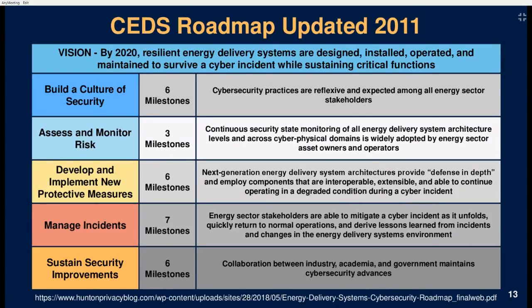I arrived at the OT community only 5 years ago after supporting DoD IT systems for over 20 years. I can attest that these are all important topics in the control system sector, not just energy. I have already alluded to the culture earlier and the need to have sensors and continuous monitoring tools. And I cannot emphasize enough the importance of a defense in depth infrastructure between control system networks and the IT or NIPRNet, and segmenting the communication of human to machine from machine to machine.